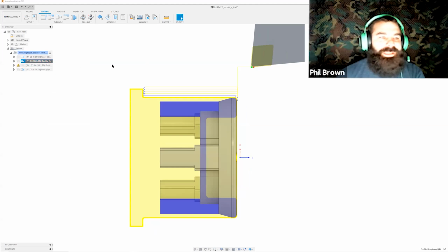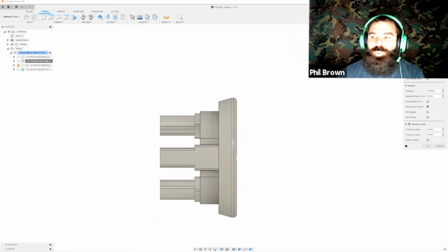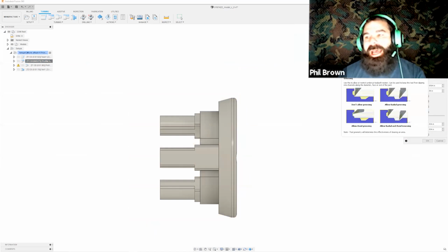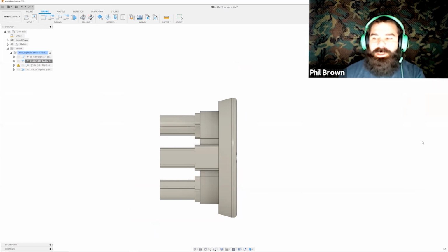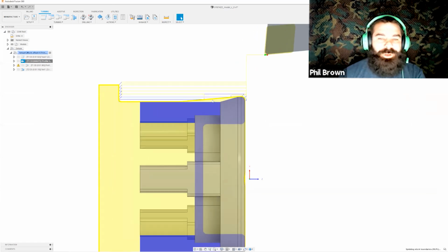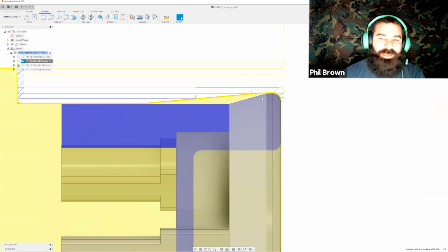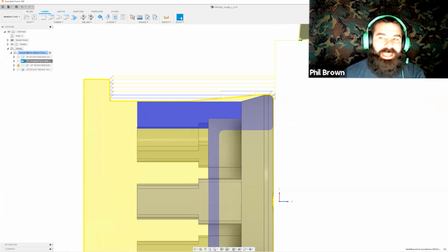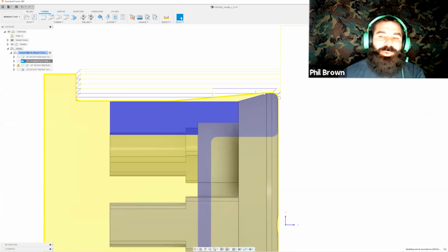Correct. Fusion 360 has the ability to do radial and axial grooving. What is radial and axial grooving? I like to refer to it as undercutting, or being able to get into those areas that in most cases you might be switching tools to use something like a grooving tool or things of that nature. So out of the gate, I'm going to stay with that 80-degree rougher to give you an idea of what's happening. Fusion 360 is looking at the angle of the tool for clearance, so it's still not crashing into my part, but I still have this nasty little bit here to rough out, correct?